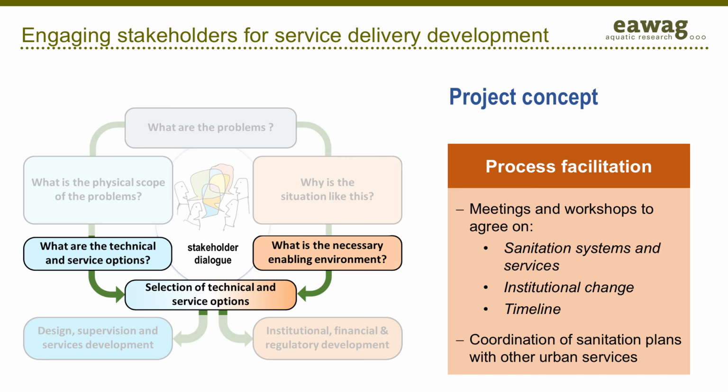At the project concept stage, it's vital to work closely with all the stakeholders to develop the technical and non-technical options and an implementation timeline they're comfortable with. Without this, the program won't be feasible or sustainable. A further dimension is to ensure that sanitation plans are coordinated with water supply, drainage, solid waste, and land use control. These all have a profound influence on the choice of sanitation options.